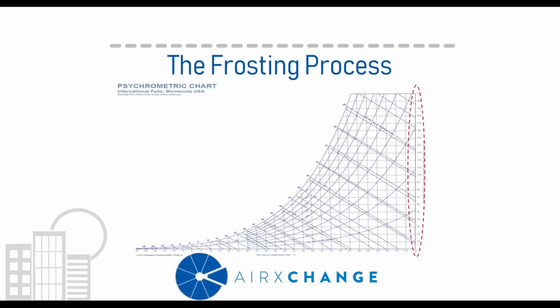The vertical axis represents humidity, starting with low absolute humidity on the bottom, and as the condition gets more humid, it moves to the top. The curved lines in the middle represent relative humidity. Relative humidity is a measurement of how much humidity is actually in the air as compared to how much there could be, starting at 0%, which is completely dry, to 100%, which is completely saturated.